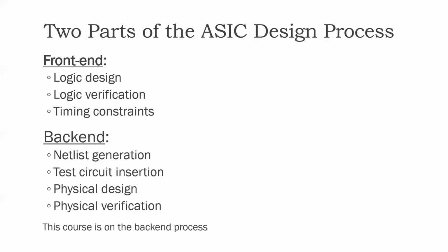So logic design and logic verification are two of the critical steps of the front end part of the ASIC design process. And then there's also what is called timing constraint definition, where the timing requirements of the logic are captured in some format. So logic design, logic verification, and development of timing constraints constitute the front end of the ASIC design process.